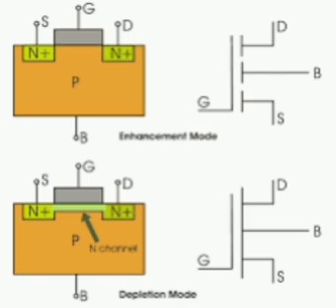Metal semiconductor junctions. Metal semiconductor junctions are of two types: ohmic contact and Schottky junction. The band profile of the disconnected metal and semiconductor can be drawn, where phi m means work function of metal, chi s means electron affinity, EFM is the Fermi level of metal, EFS is the Fermi level of semiconductor, and EC and EV are the conduction and valence band levels respectively. Formation of a Schottky junction takes place when metal and semiconductor are brought together.